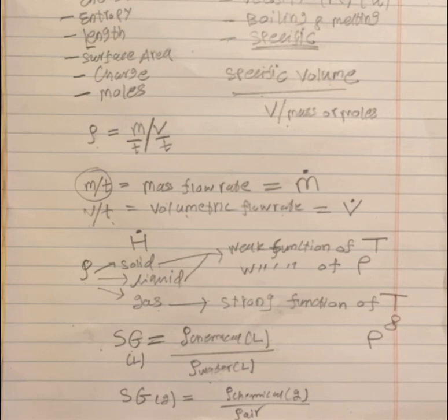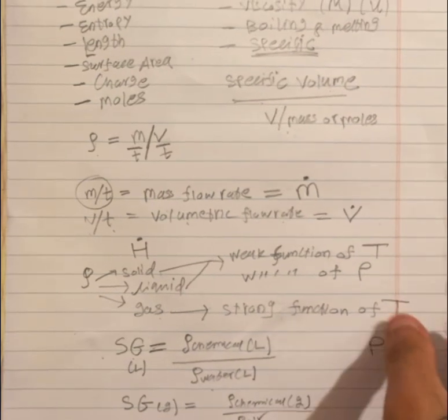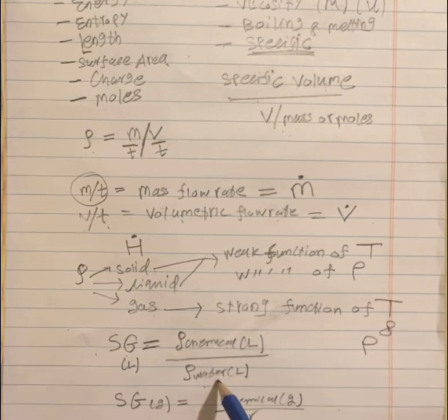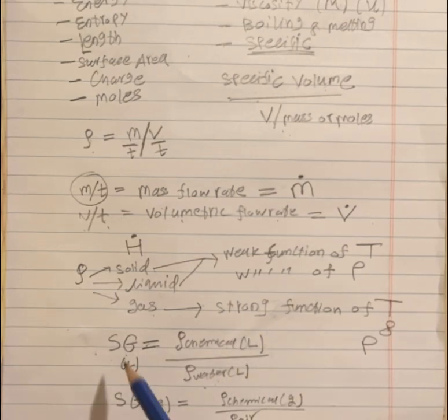It will be really helpful, and they are also used as a conversion factor. Suppose you need to know the density of a certain chemical, just multiply the density of water by the specific gravity that should be given, by the way, to find the density of the liquid chemical. So specific gravity works as a conversion factor.